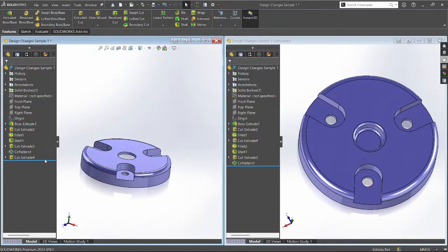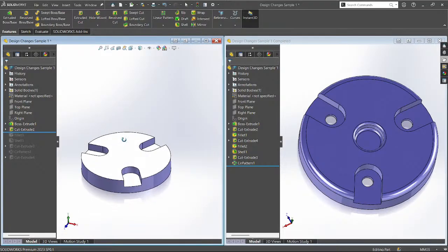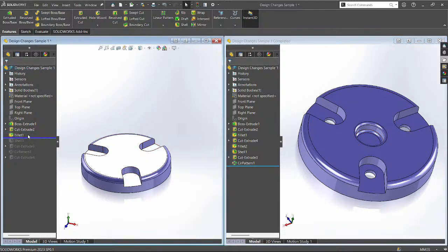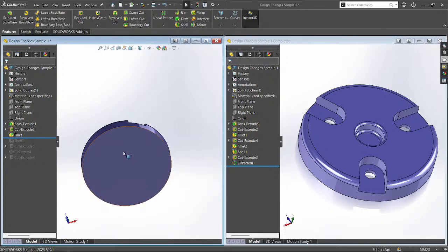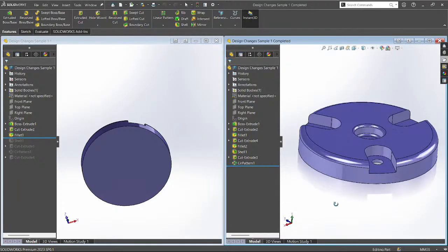Now if I just go here and skip it, and if I try to create that feature, there won't be a full cavity, right? It will be a shape like this. Am I right? Even though if I just keep it here, there's a fillet, and here also if I create that particular cutout, there won't be a direct hole as it is now, right? So what I need to do is create one particular cutout here, so that the shell feature can recognize this cavity, so that it can assign the thickness for this.